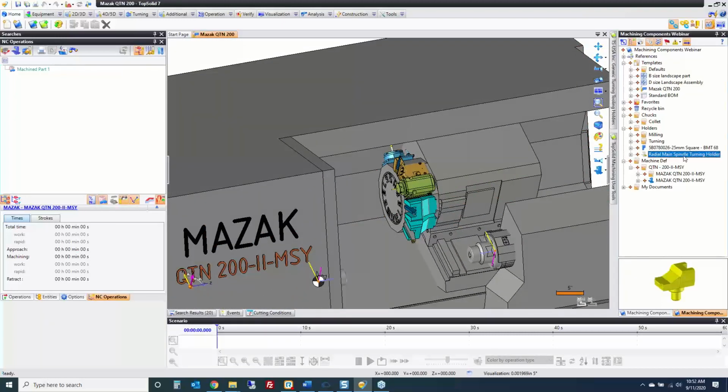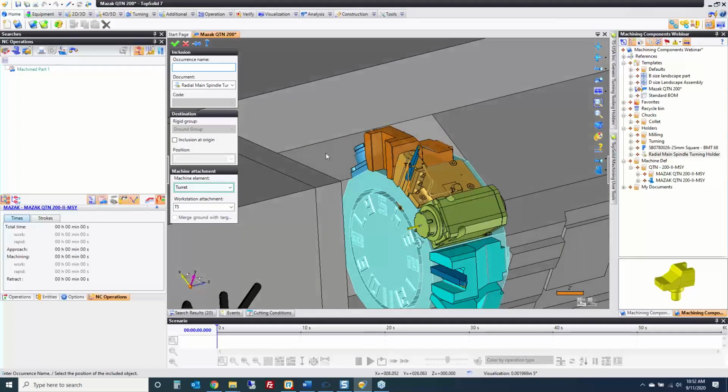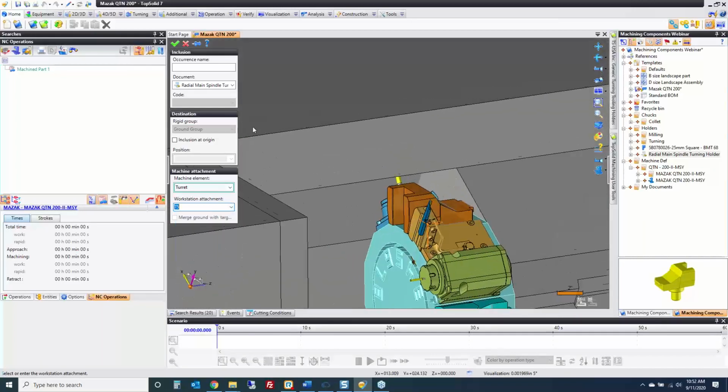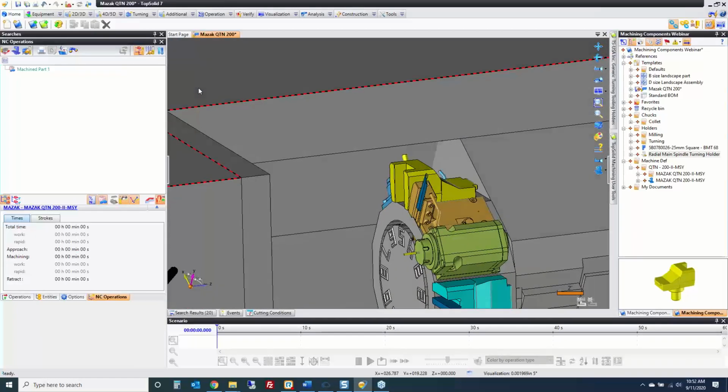Let's take this holder that we just created, drag and drop it onto the pocket I want to put it on. Notice it's right there, right? I can, of course, come through here and switch it. Let me zoom out so you can see, to be on any of those pockets. Just leave it on top for now, just for fun. We'll green check. That holder has now been included.